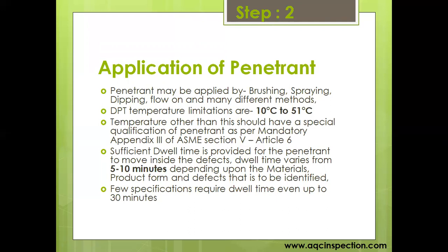After penetrant application, sufficient dwell time is given for the penetrant to penetrate into the defect. Dwell time varies from 5 to 10 minutes depending upon the material and product form. A few specifications often require even up to 30 minutes.